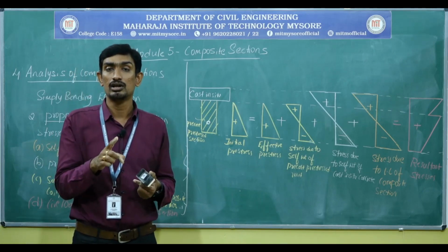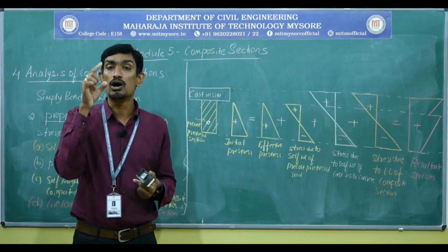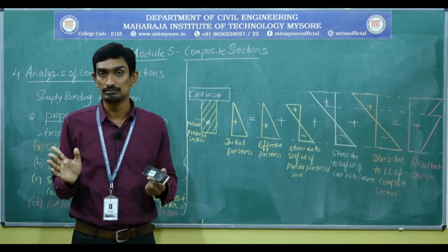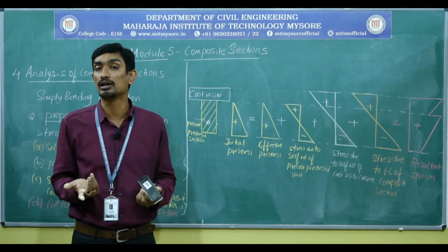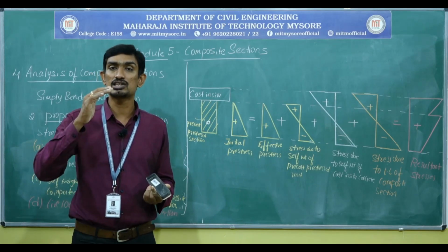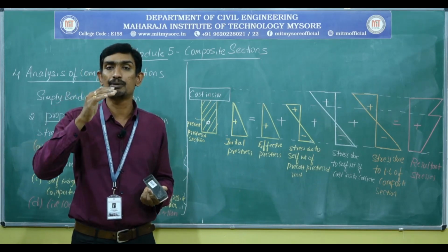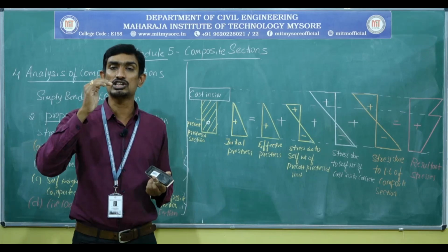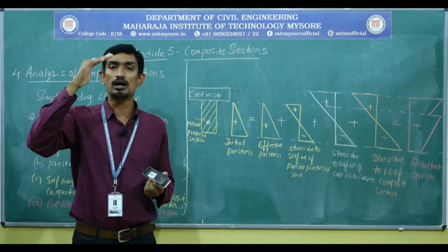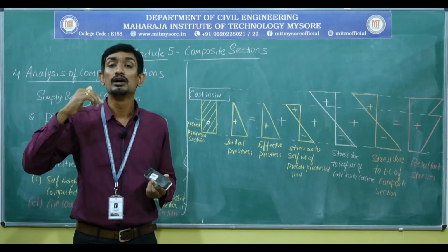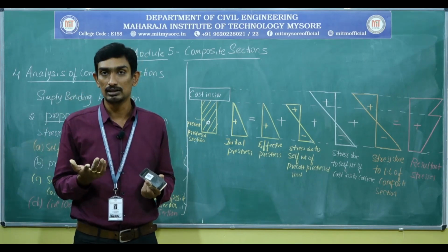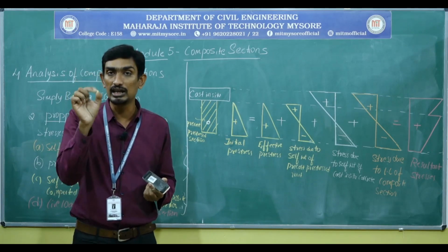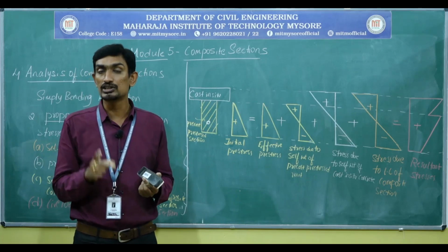If you come across a modular ratio variation, for example, if the modular ratio is equal to 1, which implies what? That means the modulus of elasticity of cast in situ and of precast is the same. No need to worry, it remains the same. If the modular ratio, that is the modulus of elasticity of precast and of the cast in situ concrete slab, varies, maybe 0.8 or something like that, at that particular circumstance the live load stress calculation varies. How do we calculate it then?